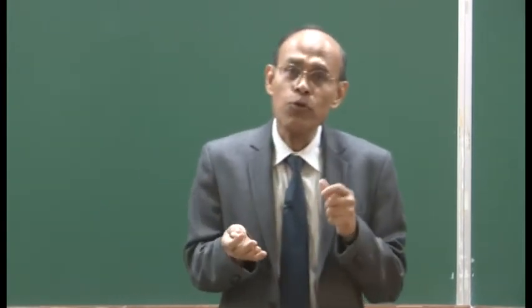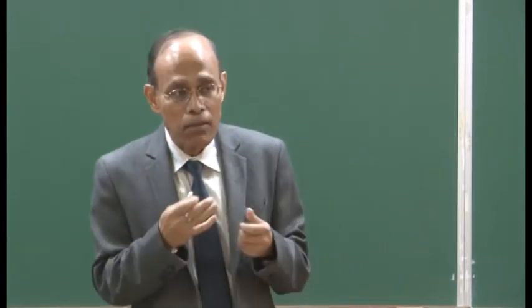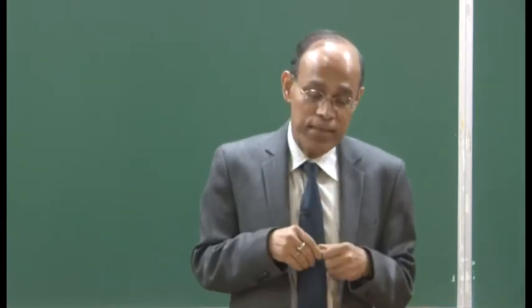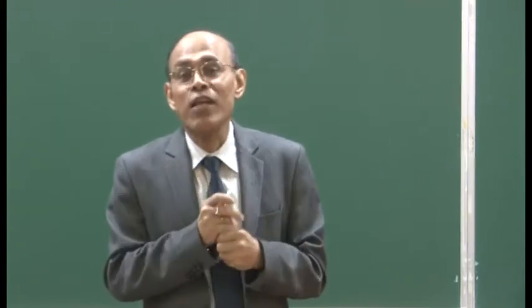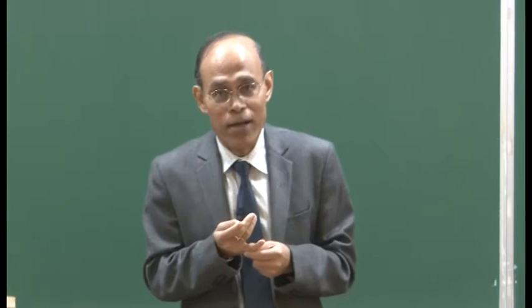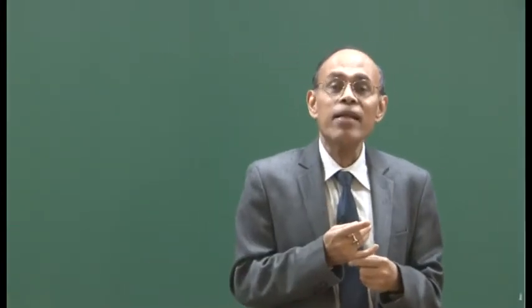And of those, if you look back at your notes or try to recapitulate, you will see that I said categorically that 4 of these variables are basically given to us. That is the input of iron and output of iron, because output of iron is 1 mole, so accordingly input is known. Similarly, the ore composition O by Fex is known, as well as the C by Fe, that is the carbon content dissolved in molten iron or hot metal. And that left us with 7.